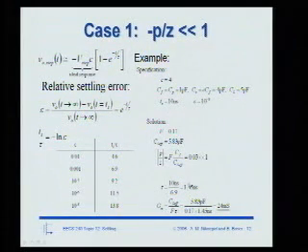And then finally, once you know the settling time, you can actually calculate what GM you need in order to achieve that settling time. So this goes back to lecture 2 or 3 when we looked at amplifier design. And there's just one little missing piece there where we said the settling time is related to tau by several factors of tau. And so here it is. So pretty simple. Okay. Any questions about this example?